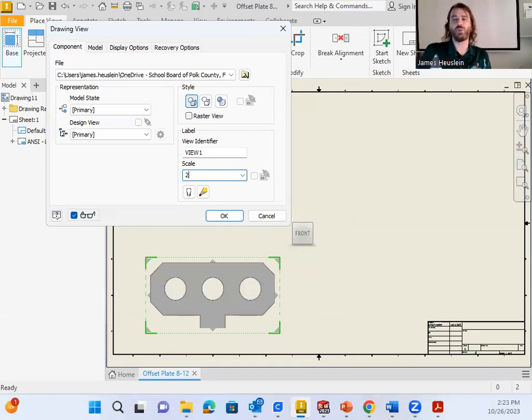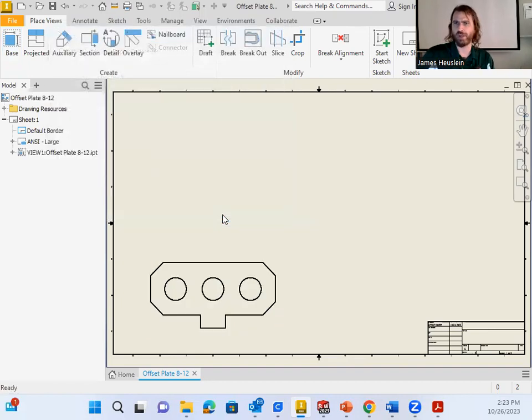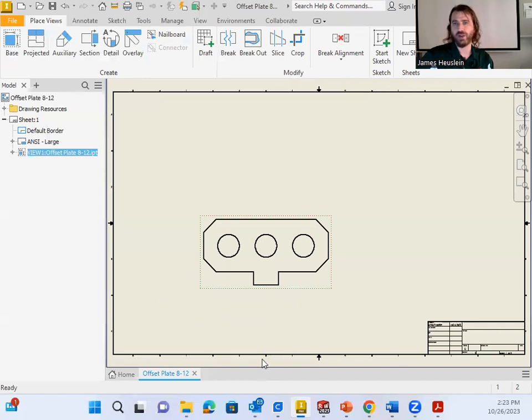And once we've set that, once we've set the viewpoint of the front, we've set the scale, we've gotten everything of our base view completed and in, we can hit the OK button here with our mouse, or we can hit the Enter key on the keyboard. Either way is fine. And once we have this base view in here, now we can move this to a location that seems a bit better, right? Because here in the corner, we're going to be adding dimensions down here and putting dimensional lines in here to communicate the information about this drawing. So I'm going to move it away from that corner just a bit, just to give us some more space, right? So let's give us some more space and put it there.